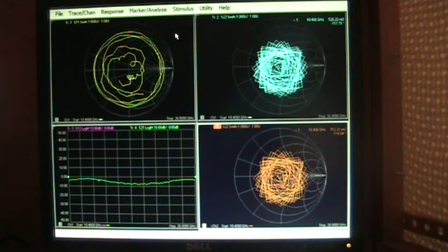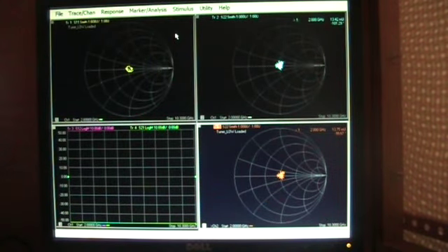This will look confusing for a little while, but we're going to be moving the tuner to its first initialized state. And then you'll see a spirograph pattern on the right side. In the upper right, this is S22 from the de-embedding of the tuner. In the lower right is the gamma source that the device will actually see. And the software will store both an S2P file and an S1P file for every position that the tuner is moved into.